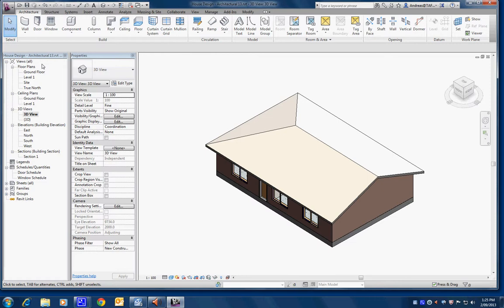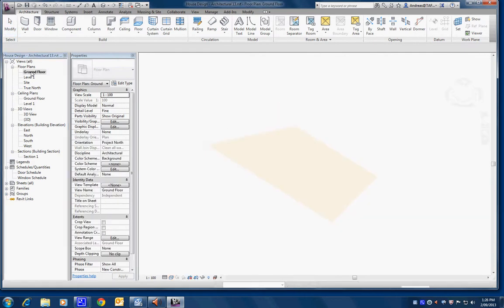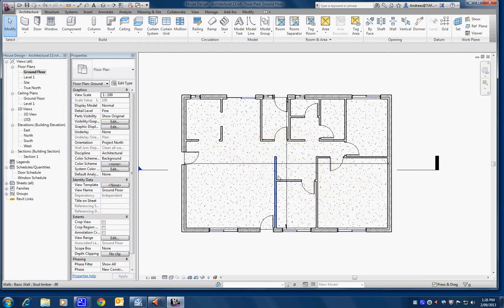We need to still talk about the footing for those of you that have not done that, and the slab, and I have updated all the instructions as well, which includes that in the instructions. Was there something else we need to look at apart from that before that? Yes, there was, and that was in relation to these openings. We haven't actually showed you how to create the openings as yet, officially, although some of you have already done it. So basically it's under the architecture, wall opening, and what it says down the bottom here is select a wall to create a rectangular opening in.